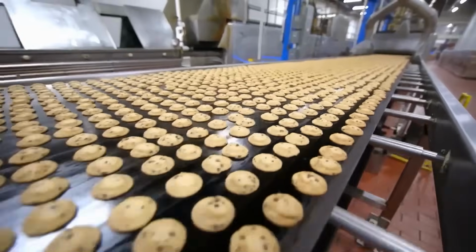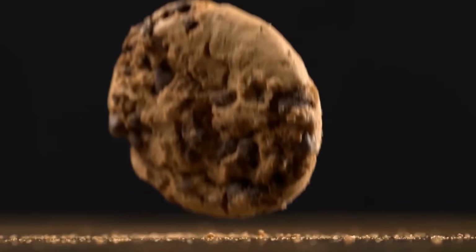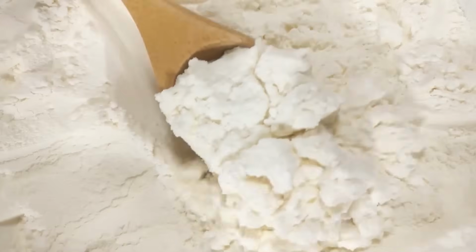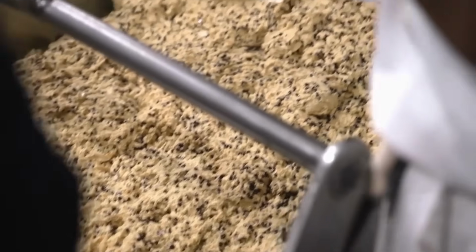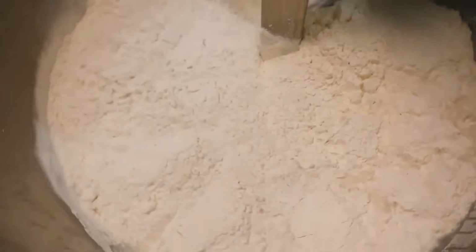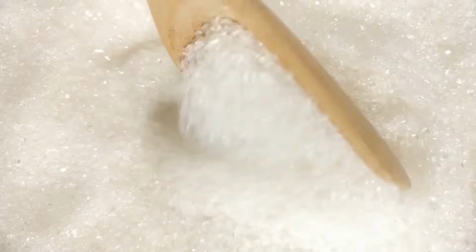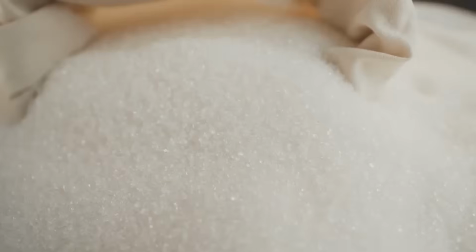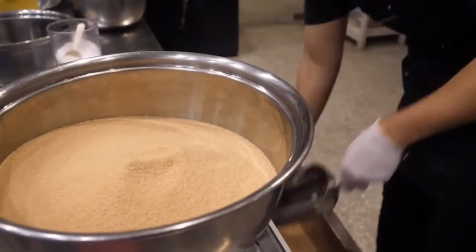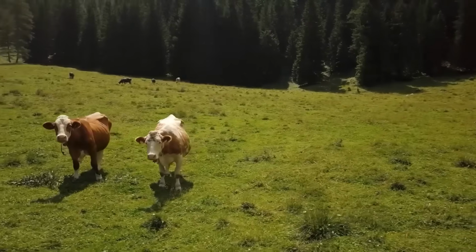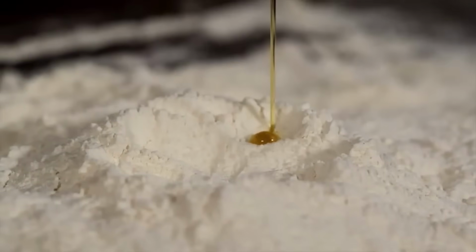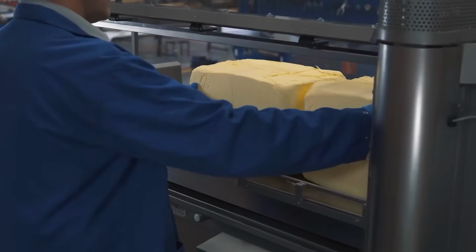Each wrapped package receives a printed date code, batch code, and line identification number using thermal inkjet printers synchronized with the conveyor belt. Packages are weighed on inline check weighers with rejection arms for any unit falling outside of mass tolerances. Wrapped units are inserted into cartons using robotic pick-and-place arms with vacuum grippers. Cartons are sealed with hot melt glue at 165 degrees Celsius and pressed under controlled pressure to ensure full adhesion.